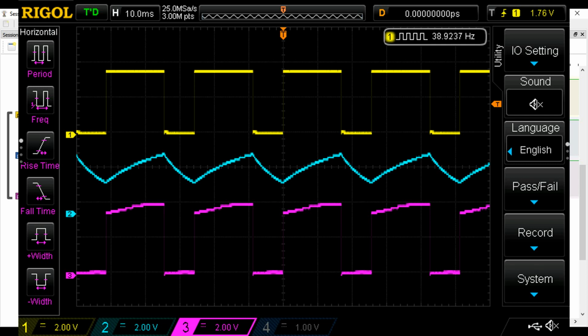The analyzer works very similar to that of the Schmitt trigger that I discussed in my recent optical counter project. If you haven't seen that video, I recommend it. I will link it below. When you probe a digital waveform, i.e. a square wave, it uses two voltage thresholds to decide if it's a 1 or a 0, high or low, on or off, etc. In a very expensive logic analyzer, you can change these thresholds, but in cheap ones like mine, they're fixed, normally by the buffer used within them.